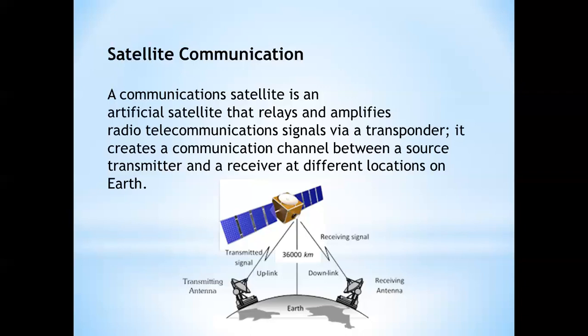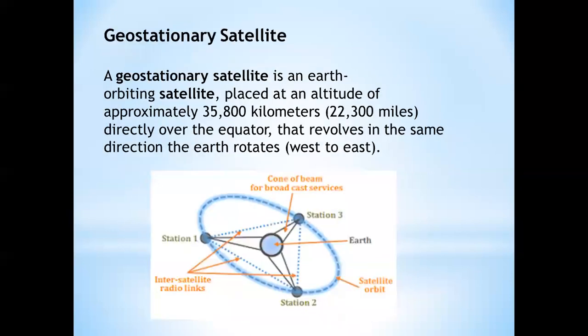Therefore, control routines such as station keeping and attitude control are executed from the control room in the Earth station. Multiple access methods such as FDMA, frequency division multiple access, TDMA, time division multiple access, and CDMA, code division multiple access, are used to allow access of the satellite to the maximum number of Earth stations. The power requirement of the satellite is satisfied by the solar panel and the set of nickel cadmium batteries carried by the satellite itself.